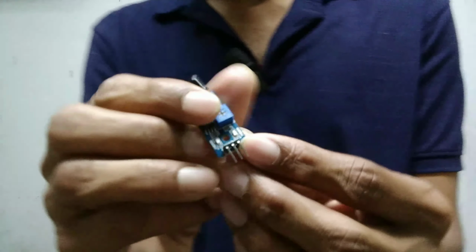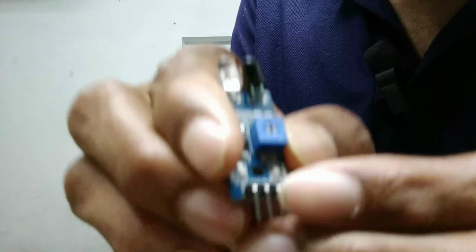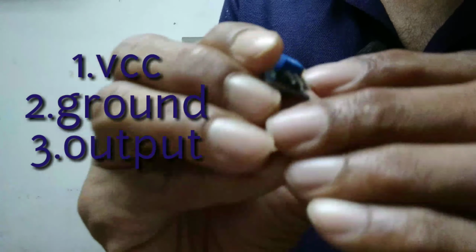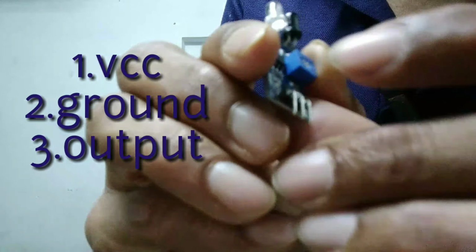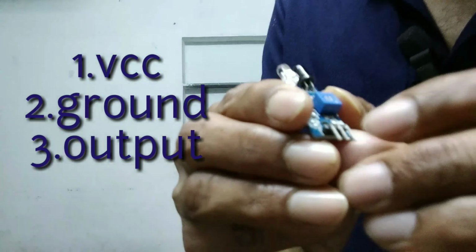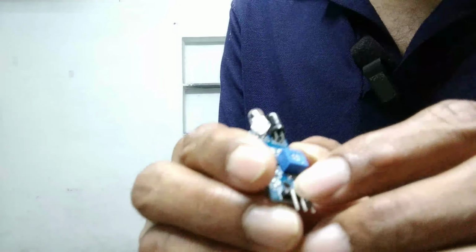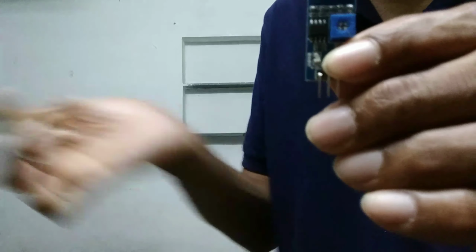The first one is the pin for VCC, the next one is ground, and the next one is the output pin. First we connect VCC to 5 volts, the next pin to ground, and the output to a preferred digital pin, one of those from 0 to 13 on the Arduino board.